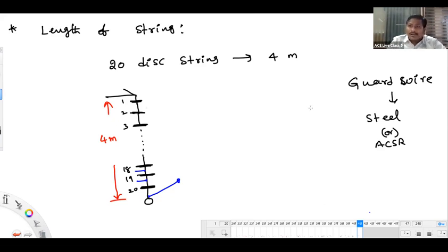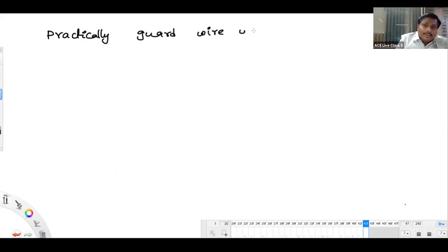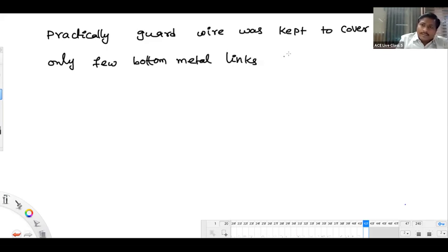I think all of you understood the point I said. So I am writing that one. Kindly listen. Practically, the guard wire was kept to cover only a few bottom metal links, such that major shunt capacitance charging currents will be cancelled.